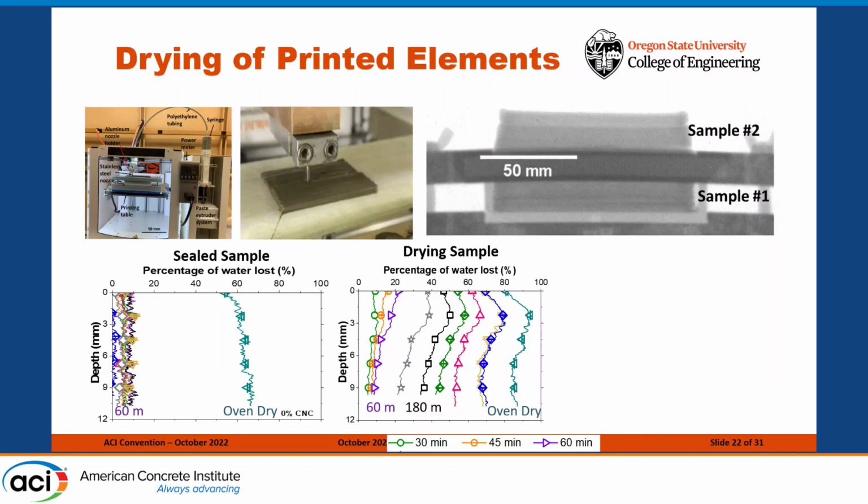But we capture most of that water until we oven dry it. The one that's exposed to drying, we have an enormous amount of moisture loss. And what's really important and what's different than almost everything else we look at, for 100 years, we've dealt with curing and we've said, well, let's not really worry too much about the sample thickness because everything's thick, right?